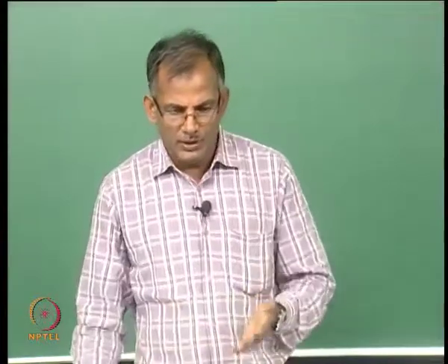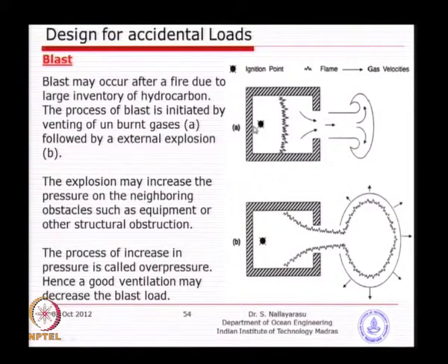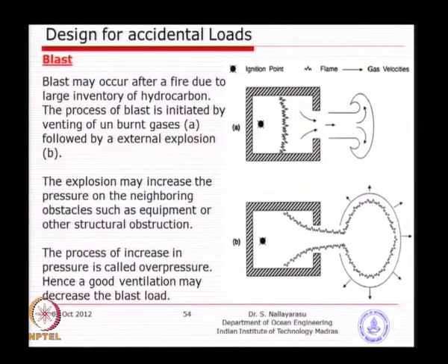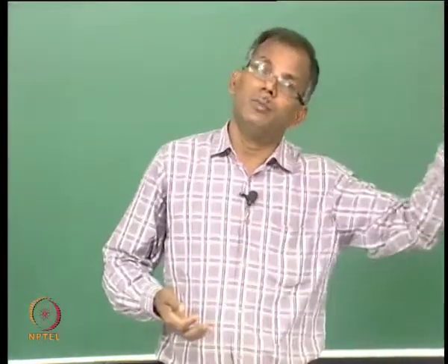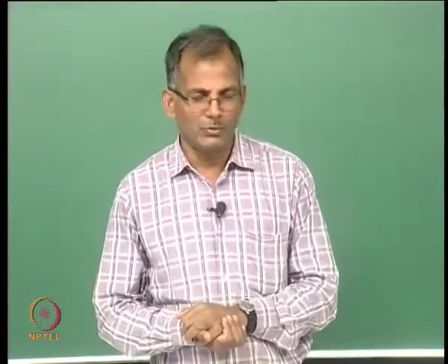Now, if you look at this typical compartment, the most important problem is the ventilation. If you do not have ventilation, what is a blast? A blast is basically an ignition of a source material. It could be gas, in the case of a platform, or it could be oil, or other types of sources which we normally do not use in offshore platforms.